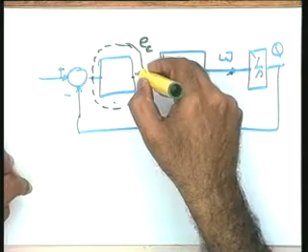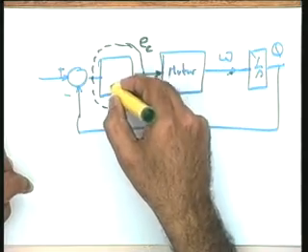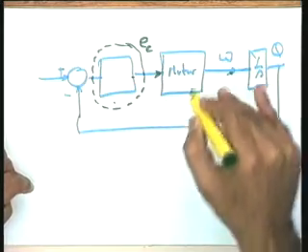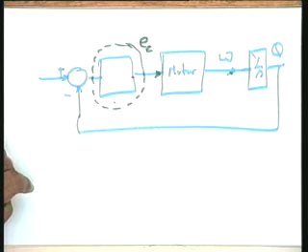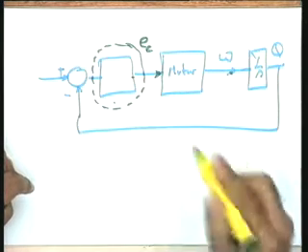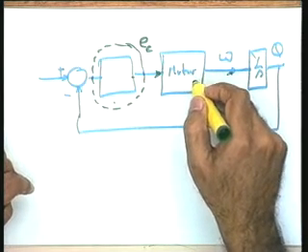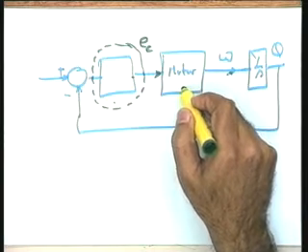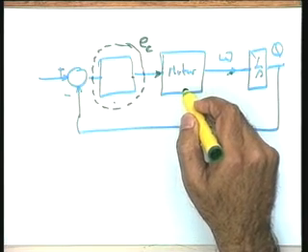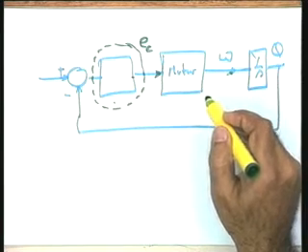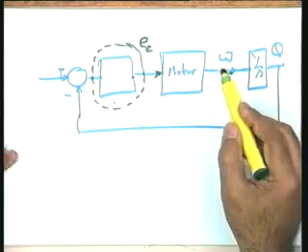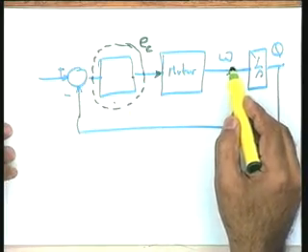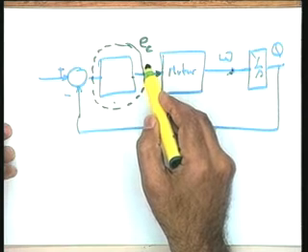Now suppose I have a device over here, which produces a carrier modulated signal, which is the signal being fed to the control phase of the motor. In that particular case, as far as the motor is concerned, it is getting a carrier modulated signal directly as an input signal. So it appears I should take the transfer function between omega and the carrier modulated signal.